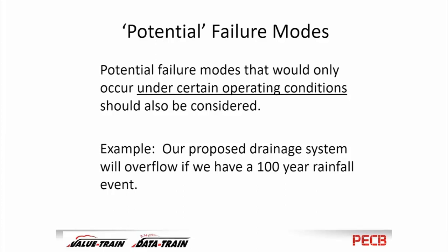One way of mitigating that was to build a giant underground tank. So, a great big hole in the ground, cover the hole over, put a pump in it, and put a system in it that would neutralize this chemical, so that when we pump it out, it would be safe. And the neutralization agent was chlorine gas.